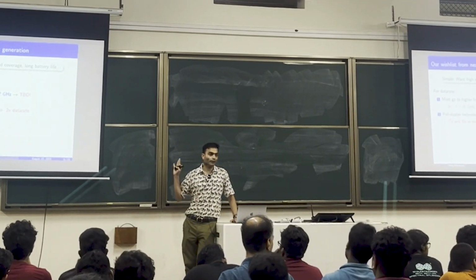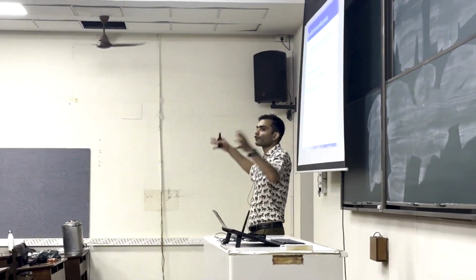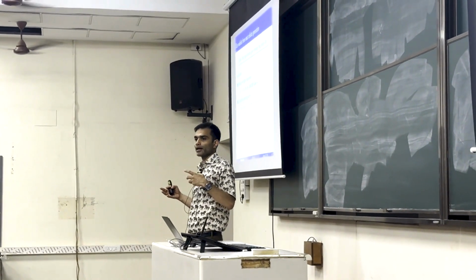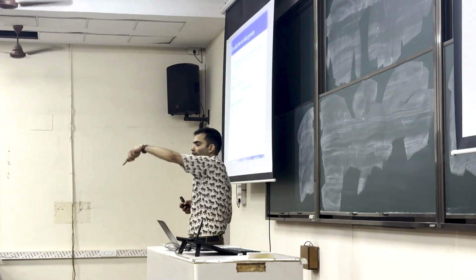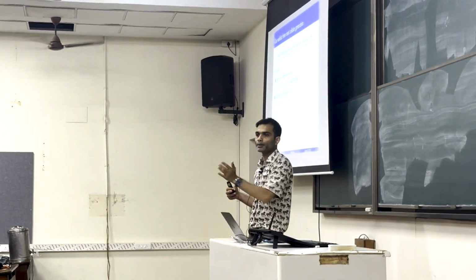So far we are talking about data. Question: why should there be so much difference between FR1 and FR2? It's a good question. Why should FR1 and FR2 be so far apart? Because they are serving different applications. FR1, you can imagine you with your mobile phone walking around the department, because you need coverage, you need the wave to be able to bend.